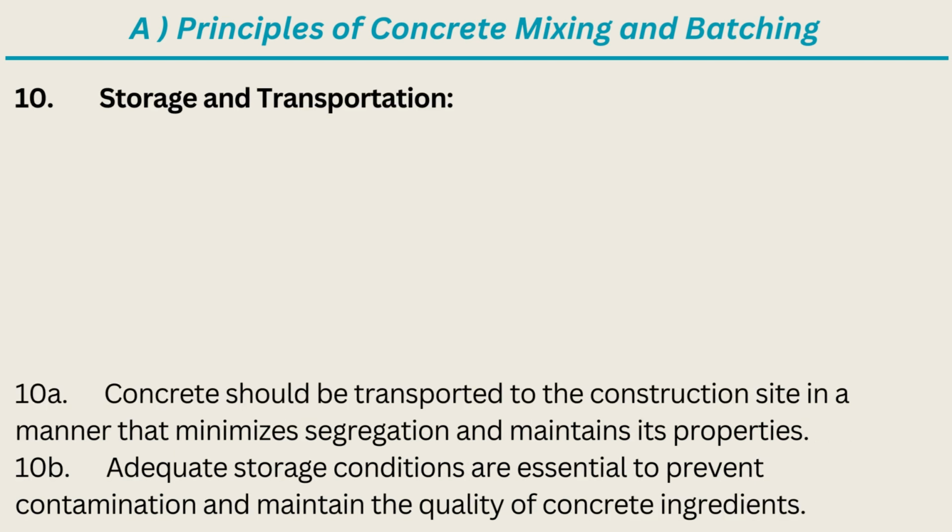10. Storage and transportation. 10a. Concrete should be transported to the construction site in a manner that minimizes segregation and maintains its properties. 10b. Adequate storage conditions are essential to prevent contamination and maintain the quality of concrete ingredients.